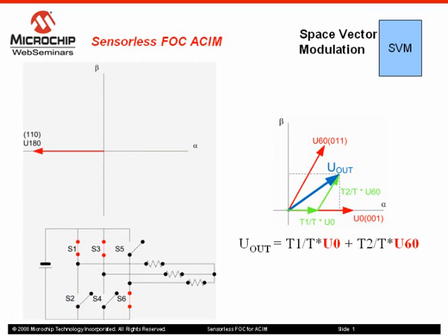When all three outputs are connected to plus or minus voltage, the state is considered null because they do not generate line-to-line voltage. The other generated states are separated 60 degrees from each other, as shown in the animation. The SVM produces all the other voltage vectors as a sum of two adjacent vectors. The linear combination of the two vectors is reflected in the duty cycles of the generated PWMs for each phase.